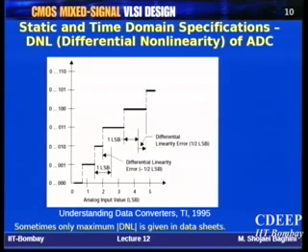Because you expect the next transition point to be 1 LSB plus this, but now it is 1/2 LSB plus this. So you have a minus 1/2 LSB error. This is called differential nonlinearity. Here it is the opposite situation. For example, here, corresponding to 011, this is the transition point.